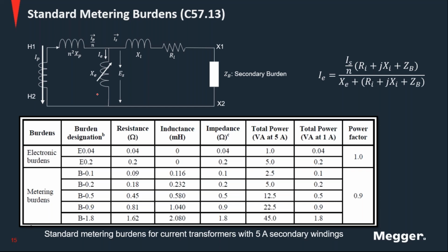Other things have been mentioned here. For example, you do a winding resistance test on the CT and you don't perform a proper demagnetization. Or sometimes you do perform the demagnetization, but some CTs have too much core, and then the demagnetization doesn't work as intended, and you will have problems with the increase in the excitation current. So there are many different factors that can increase the excitation current, and I have only mentioned a few of them.